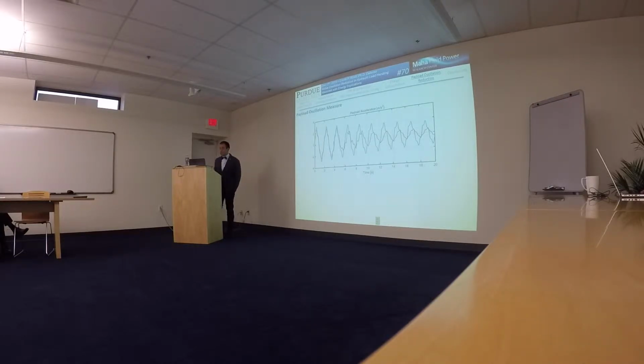Another important thing is how to evaluate the effectiveness of the controller. I did this using the definition I'm about to explain. Here is a result example: if we define two different peaks of this oscillation, separated by a number n of periods, we can define a logarithmic decrement, and then an equivalent damping ratio.